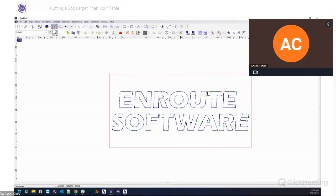So the first thing that we're going to do is click on our paneling tool. So I'm going to click up here and, whoops, wrong one. I'm going to my plate settings, and I'm going to hit define plate panels. Now you're going to see this, and I intentionally did it this way because I wanted you guys to see this. This is an option that has to be turned on in order for this to work. It's called clip to plate or clip toolpaths. It needs to be turned on. I can go ahead and say yes, and it'll automatically turn it on for me.